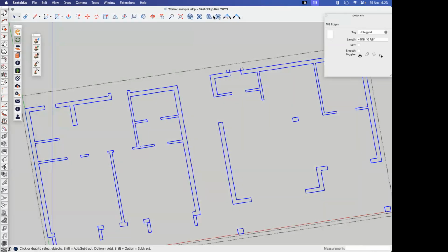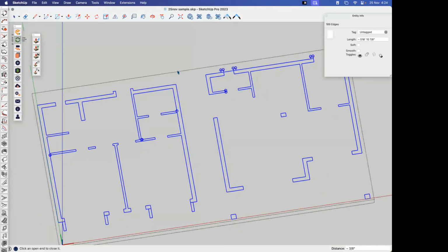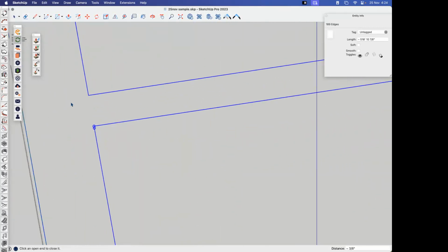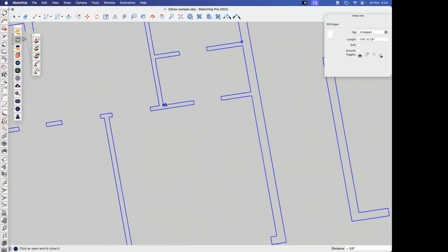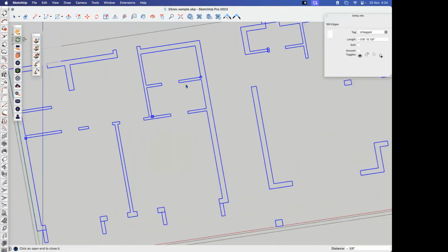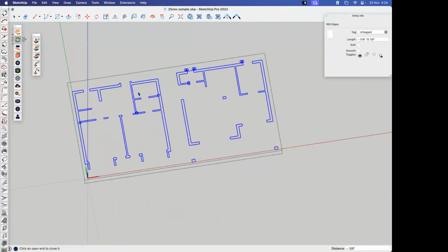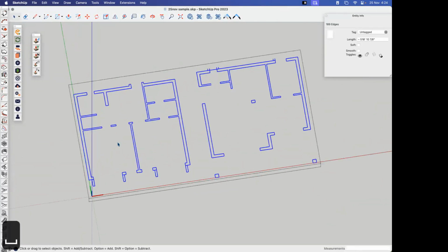For Windows users, you can just right click and then click on the toolbar for Edge Tools. So I'm going to find edges. The moment I do that, I can see where all the naked edges are. There's one here, there's one here. You could have multiple in your plan. So I'm taking a smaller plan. This could be multiple floor plans in one. And then there's a command to directly fix the gaps.